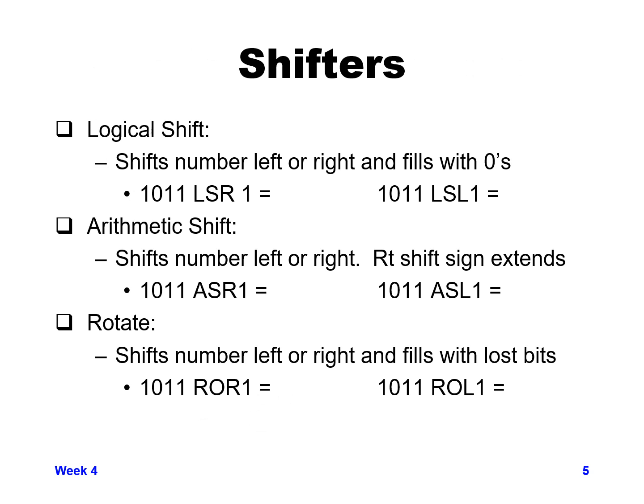As mentioned at the beginning of this week's topic, for ALUs, one of the other common functions is a shift function. There's a variety of different shifting activities that you can do. The three main groups of types of shift are a logical shift, an arithmetic shift, or a rotate. I'll go through how each of those functions works here.